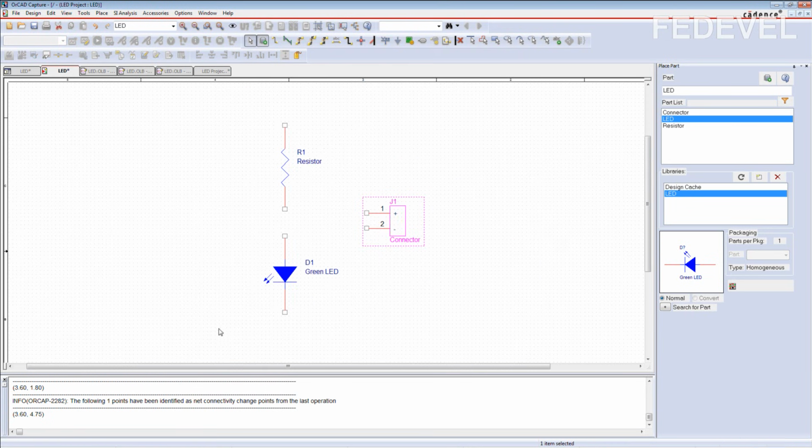If you would like to connect the components, use this button, place wire, click, and just connect it. If you would like to interrupt drawing the line, press Escape.